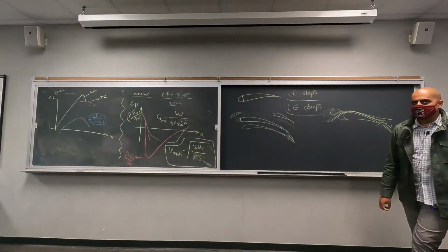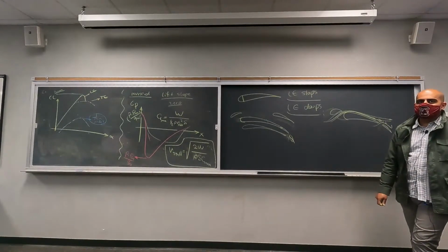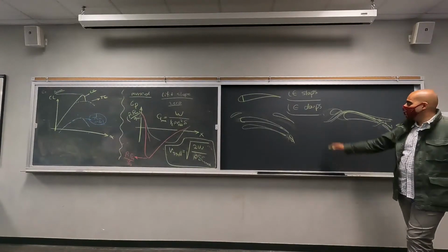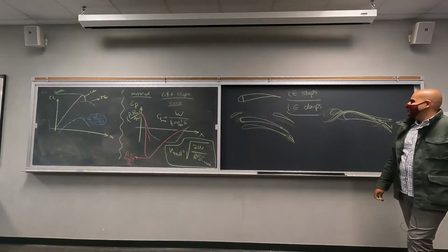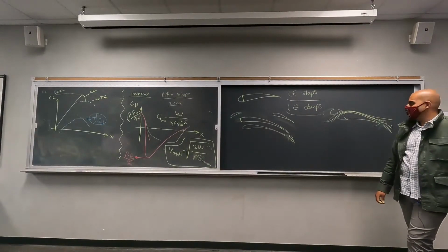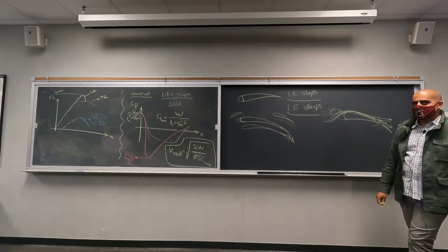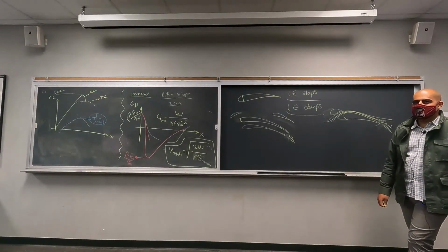Yes. On that slat that you have above, would the flow separate on top of that? It would just be minimal. On top of this, yeah, we will definitely have flow separation on top of this, but the contribution of that separation is not going to be that much, right? So you're not adding to the problem. You're definitely removing some of the problem, like delaying the problem. Okay.